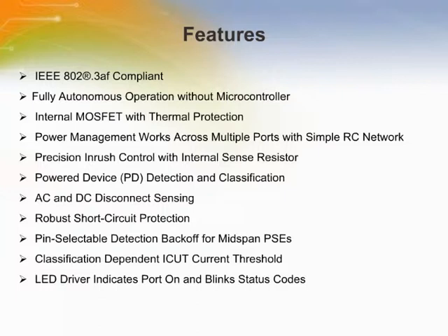The LTC4263 is an autonomous single-channel PSE controller for use in IEEE 802.3af compliant Power over Ethernet systems. It includes an onboard power MOSFET, internal inrush limit, current limit, and short circuit control, IEEE 802.3af compliant power device detection, classification circuitry, and selectable AC or DC disconnect sensing. Onboard control algorithms provide complete IEEE 802.3af compliant operation without the need of a microcontroller.